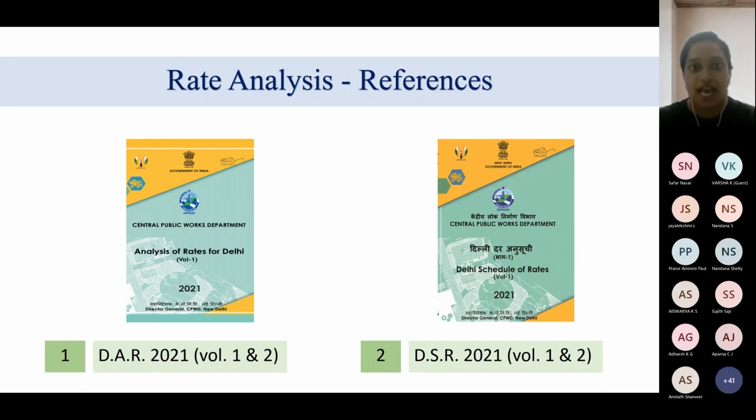I'll give another example. You're supposed to cast a slab for a building. You can do it either way. You can employ 10 people to mix and place the concrete, or you can use 5 people and a machine in order to cast the slab. This is an alternative. You can reduce the number of men and increase the number of machineries, or you can use only men. The choice of that method of casting the slab will decide what will be the rate of executing that particular work.